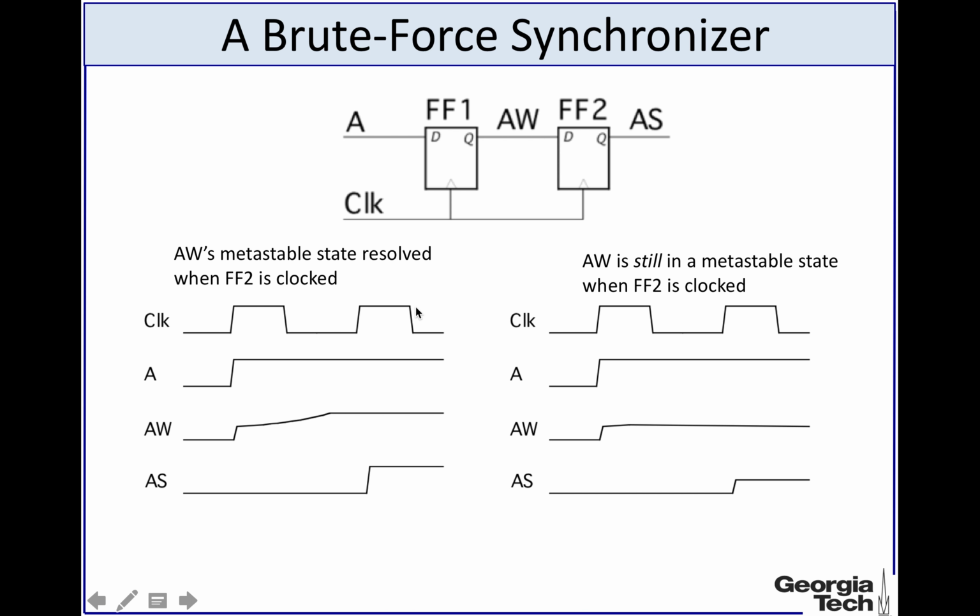Alright, so one way of resolving the metastability, not resolving per se, rather a way of making sure that the metastable state is not propagated into the rest of the circuit, is to use a synchronizer. A synchronizer is essentially a bunch of D flip-flops connected in a cascade.